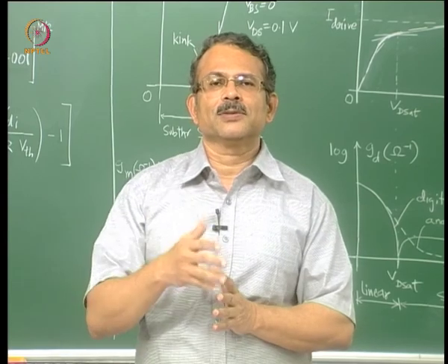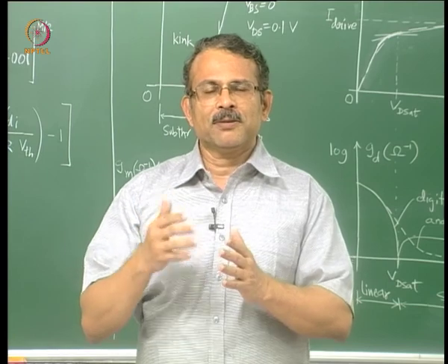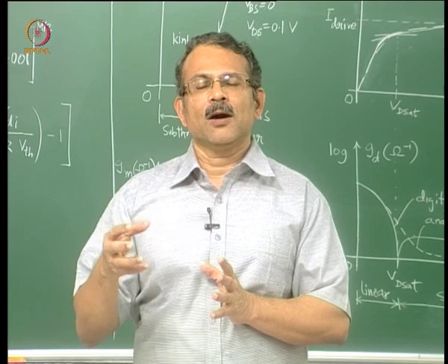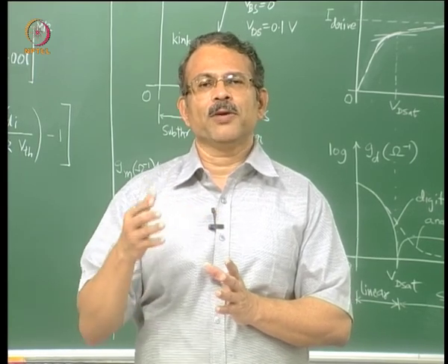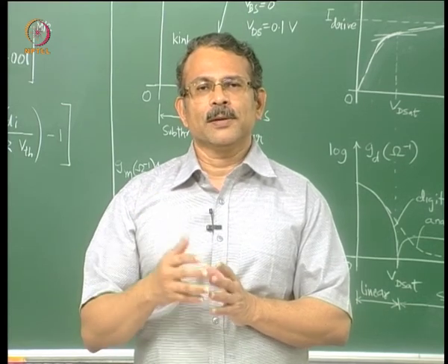The continuity is an important requirement because we discussed the method of solution used, for example Newton-Raphson, where derivatives of the model function become important. The derivatives of the model function also become important in accurate modeling of the distortion, where the shape of the waveform is very crucial in modeling.